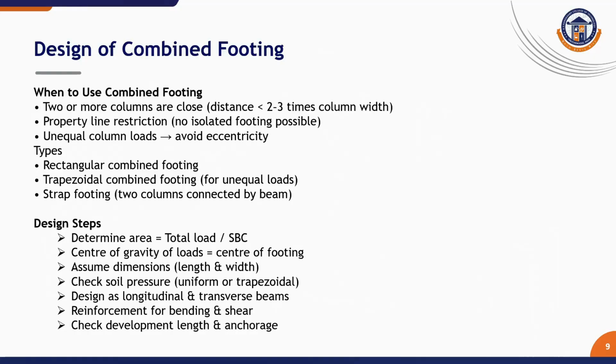Bars at both faces, its thickness has to be less than or equal to 200 mm. Standards ratio check: H by T has to be greater than 12 for braced and greater than or equal to 8 for the unbraced wall. Use interaction diagram for combined axial load and the moment.